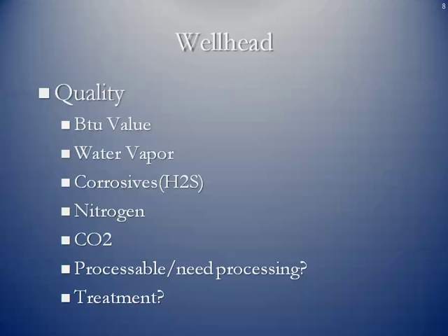And then the question of whether or not the gas is processable. In other words, can it be processed? Is the BTU content high enough to extract natural gas liquids, which are valuable on their own? The other side of that question really is, does it need processing? The pipelines are only going to accept a certain maximum amount of BTU content. If you think about it, something volatile like propane, which I think we're all fairly familiar with, you can't have that in someone's home hot water heater. You also can't inject propane into a boiler at a power plant. You will literally have an explosion. And then any other kind of treatments.